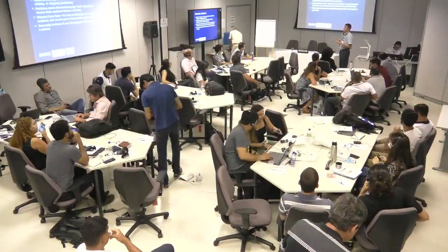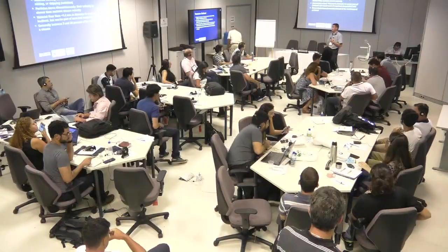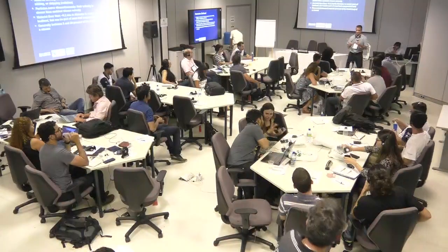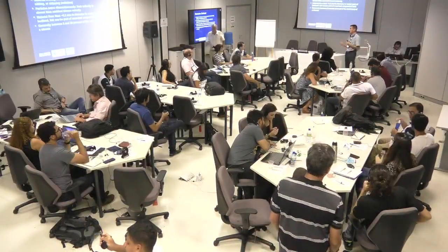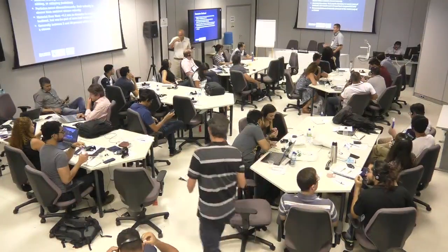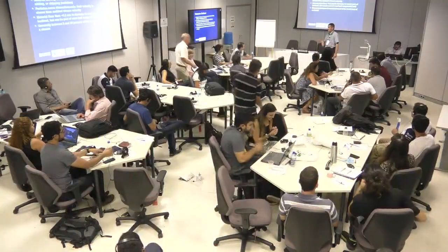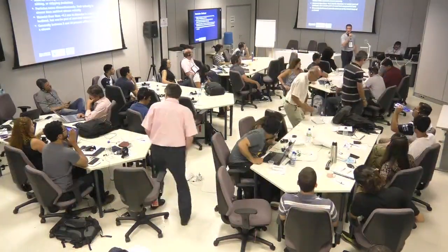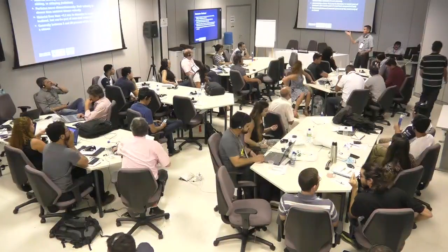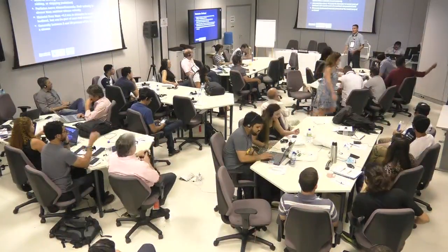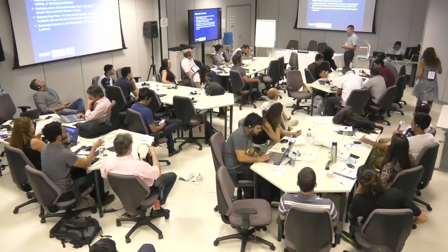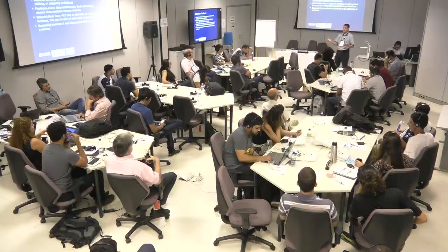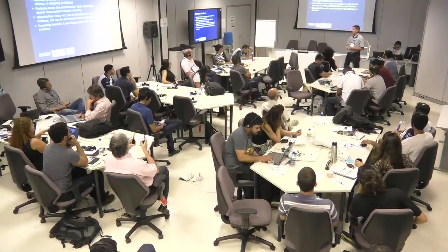So this is, as I said, material moving on or near the stream bed. It can move much more discontinuously than the suspended sediment. But to take that into consideration as we think about the sampling, the material finer than 0.2 millimeters is rarely ever found on the bed. And I think Walzon asked this morning, Molly answered, it's generally between 5 and 20% of the total load, depending on your system. But it could be 90% of your problem that you're trying to address. So in some systems, you may want to measure the bed load.